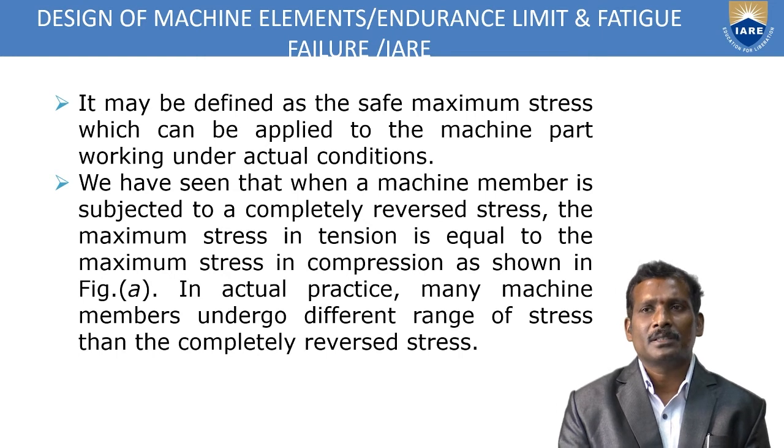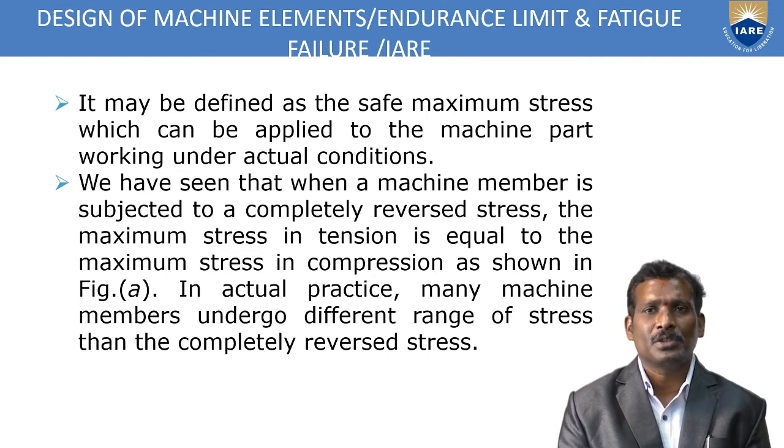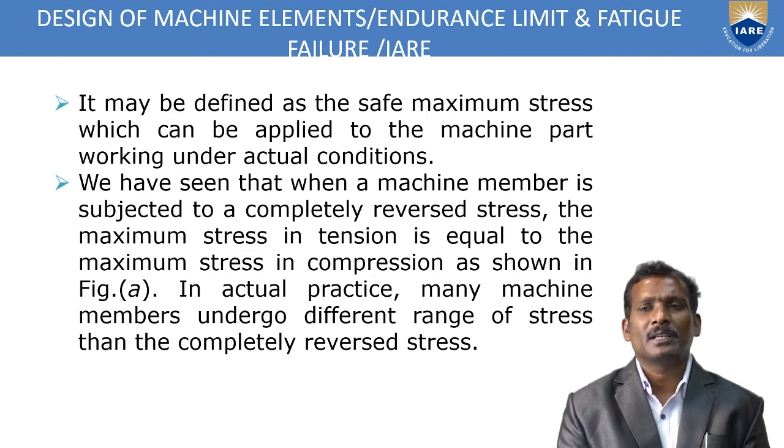in tension is equal to the maximum stress in compression. That's why the maximum and the minimum stresses are equal here, and that's why the mean stress is 0. In actual practice, many machine members undergo a different range of stress than the completely reversed stress.